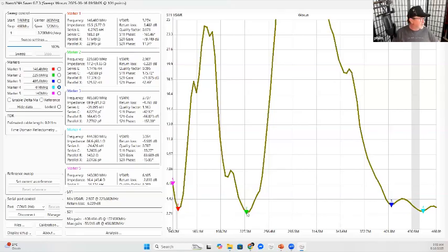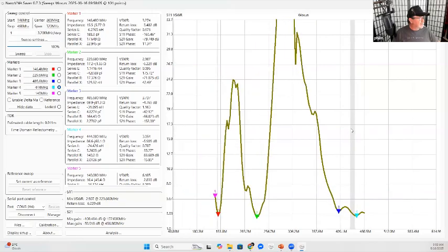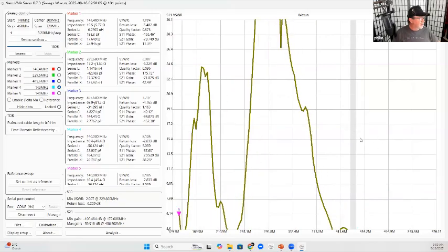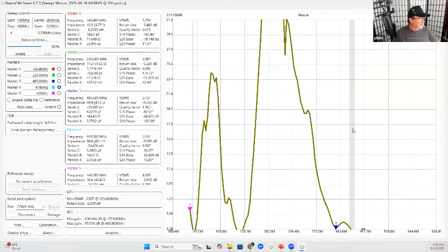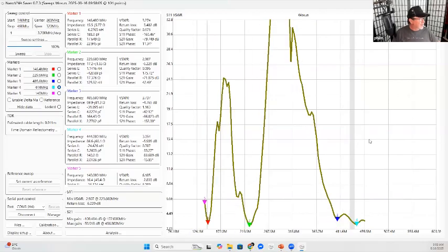And if I look at 2, you can see that the VSWR is 2.907. So you can see all the way through here. I'm just scrolling to try to collapse this a little bit. Okay, so the VSWR is not particularly great on this antenna. But what I could do is save the sweep.